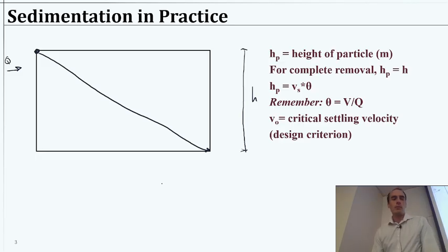So the amount of time that we have is our hydraulic residence time, right? That's going to be how long we have until the water leaves. It's a very simple system. We're not well mixed. We're doing laminar flow, so it's just a constant, slow flow to allow it to do that. We're always going to design these to avoid any turbulence to kick the particles around. We just want nice, gentle flow.